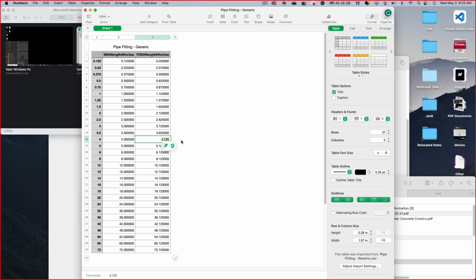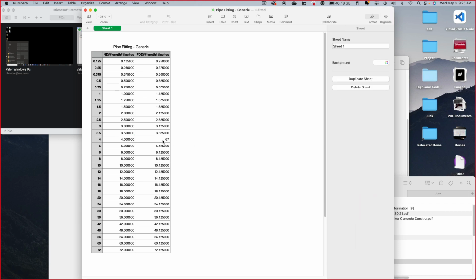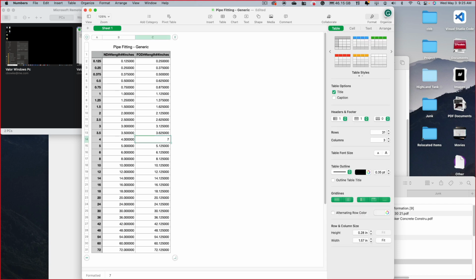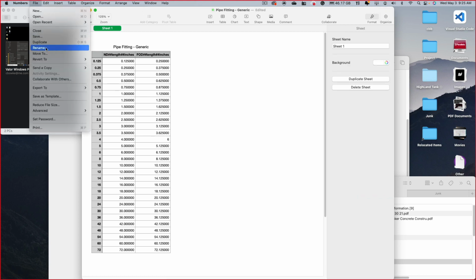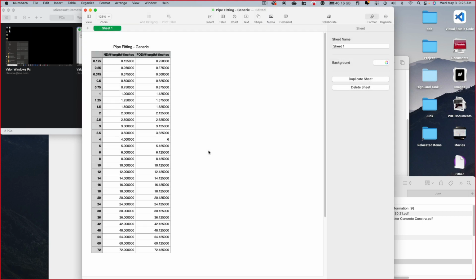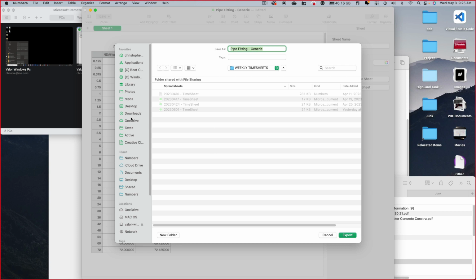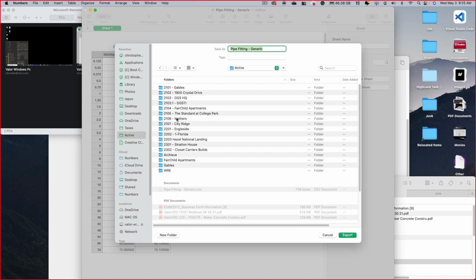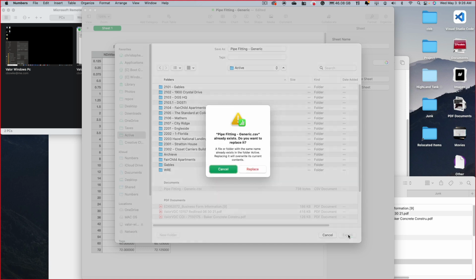So let's say this 4-inch one here, I want to make it 6-inch diameter, not 67. Okay, come on, let's try that again. 6, and then I can export the table as a CSV, and you can do all this from Excel. It's just Excel is a little bit more, I like to use the word clunky, because it gives you all kinds of options that people rarely use. So where does it store them? I guess it's all within Revit. Yeah. It's stored within that.